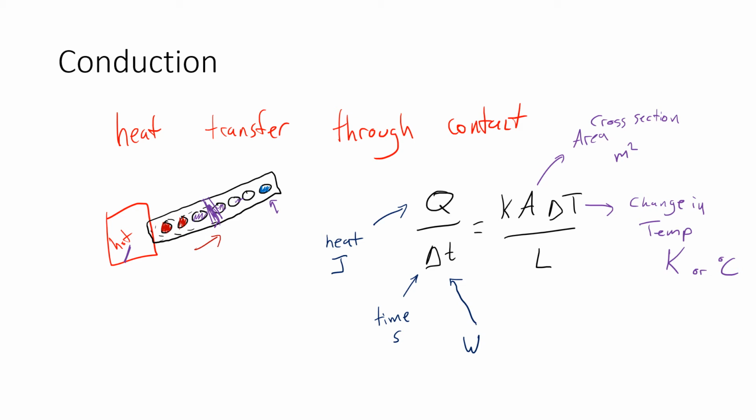So they have the same slope, they have the same width per degree. If it gets 1 degree hotter Kelvin, it's going to get 1 degree hotter Celsius. They have the same size in that respect, so it doesn't matter as long as it's a delta T, and it's very often going to be a delta T. As long as it's a delta T, you can use either one of these two. If there's no delta, you have to use Kelvin.